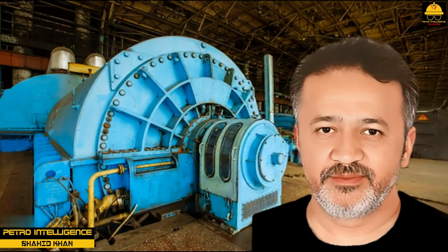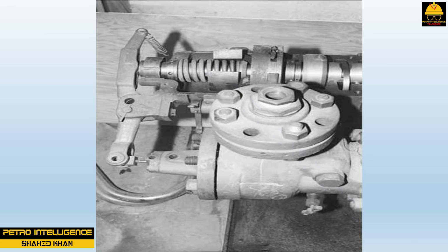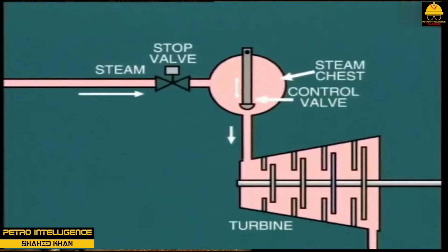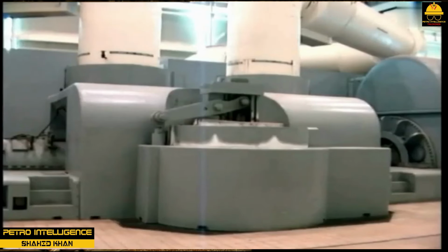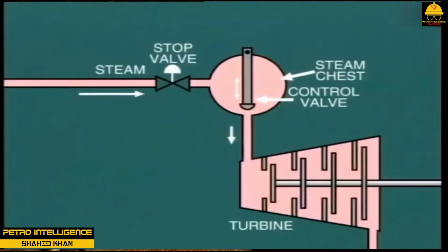Governing mechanism. The governor, as shown in the picture, is designed to automatically regulate the speed of the turbine. A shaft-type governor is located internally and mounted to the shaft. Centrifugal force causes the weights to rotate. The weights are constrained by a spring. As centrifugal force increases, the weights move farther from the central shaft, compressing the spring. The rotating spindle is attached to a fixed sleeve, which controls a fulcrum lever. The lever is used to position the governor valve.